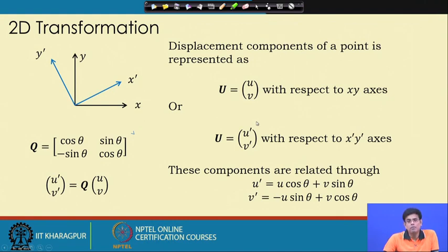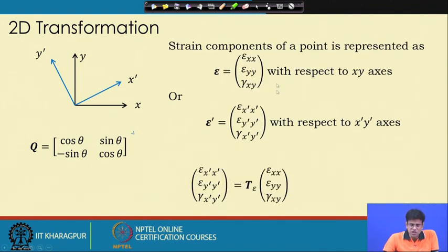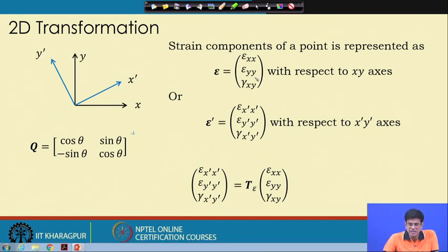Now our main objective is to derive strains, which we know from our strength of material concept, and that is why I started with the 2D problem. So, let us see how we can transform the strains. Now essentially strains are here. It should be noticed that I am using gamma xy, the shear strain, which is essentially 2 of epsilon xy. So, we keep it in this format, so here we will have some benefit of doing that. Now, Q is this, so essentially strains will be transformed here.